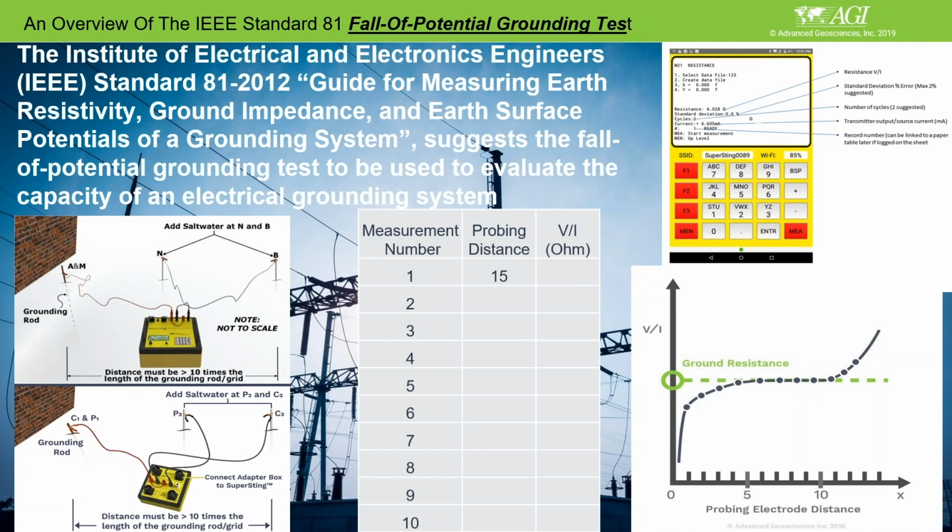Okay. When this grounding grid is installed, then this has to be disconnected first if it is already installed. So you need to connect the grounding grid from the building, disconnect it first, and then connect to your instrument. The A and M electrodes have to be shorted, or both connected to the same grounding grid. Later on, you need to connect the current electrode, and then it will be shorted, as I said.